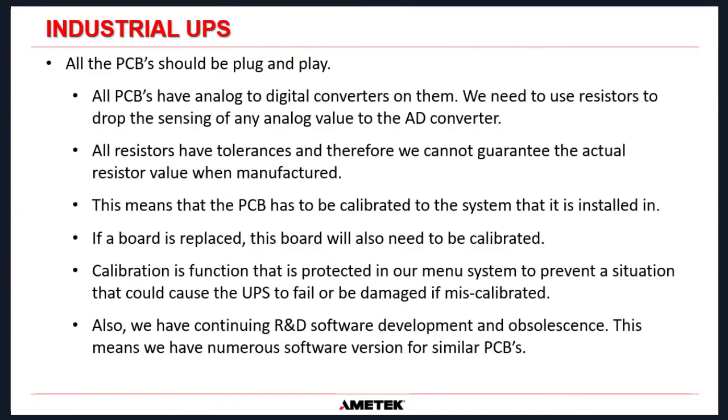Another common misconception, everybody says this: all the PCBs should be plug and play. We should be able to supply you any board and anybody should be able to install it. That would be fantastic, but unfortunately all PCBs have analog to digital converters on them, and we need to use resistors to drop the sensing of the outside world, the analog values, into the analog to digital converter, so we convert that analog signal into a digital signal, and then the UPS will decide what to do with all of those inputs.